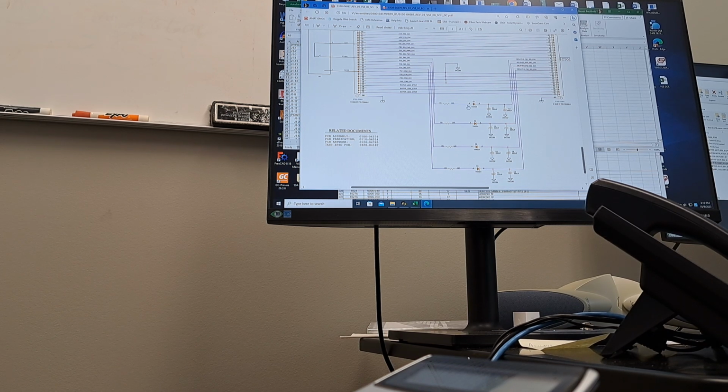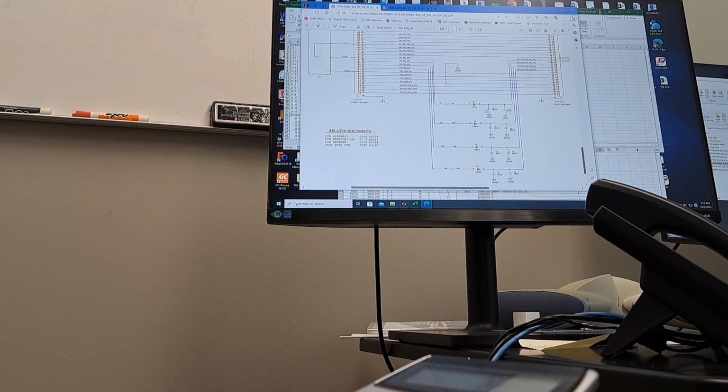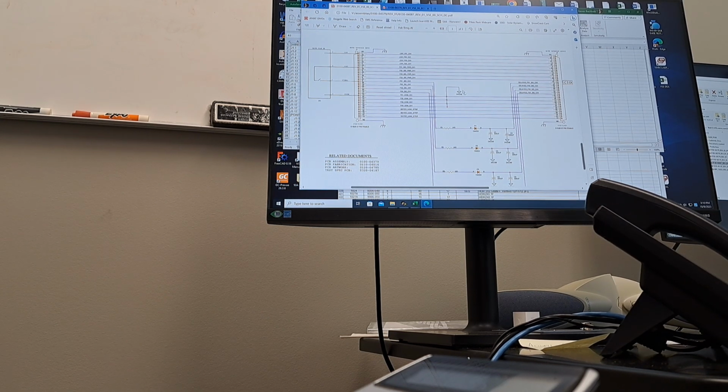We can't test this resistor or this diode because of that. But we can test these capacitors. And they're in parallel, just like for ICT or anything else. So you're not going to be able to test C1, right? But you can test C1 plus C2. So what you're going to do is say, okay, those go from J2 pin 9 to 24 comms, so you can just pick one, J2 pin 13.